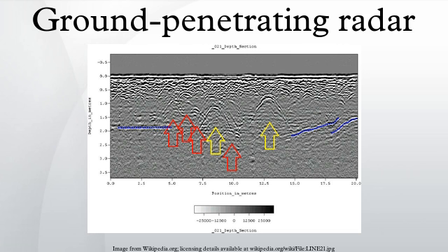Three-dimensional imaging: individual lines of GPR data represent a sectional view of the subsurface. Multiple lines of data systematically collected over an area may be used to construct three-dimensional or tomographic images. Data may be presented as three-dimensional blocks, or as horizontal or vertical slices. Horizontal slices are essentially plan view maps isolating specific depths.